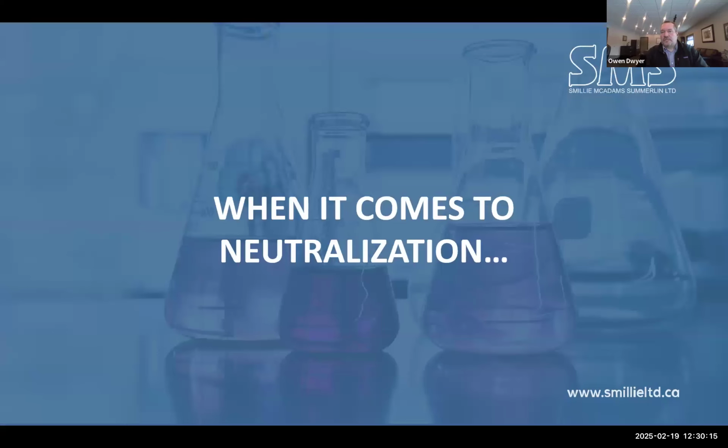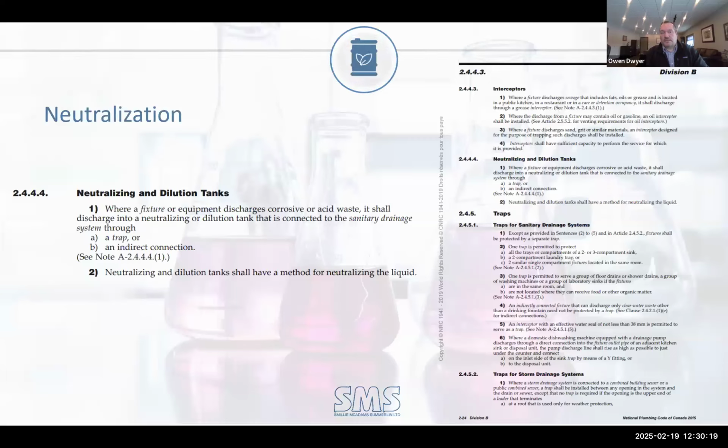Whereas when it comes to neutralization in the national code, this is what it's giving us. So 2444, neutralization and dilution tanks, specifically where a fixture or equipment discharges corrosive or acidic waste, it shall, again, shall means must, discharge into a neutralization or dilution tank that's connected to the sanitary drainage system through a trap or indirect connection. And sadly, the detail we have to follow is in 2 here.